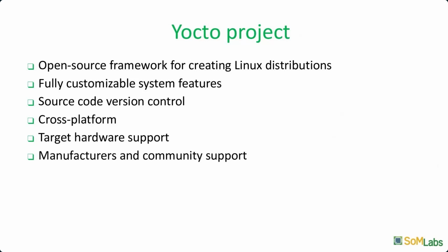It is, of course, an open source framework that you can use for any hardware with provided software layers with support. Yocto is fully customizable for the designed application, so we can choose the libraries, system tools or Linux managers that you want to include in the final system image, and everything is built from source code.